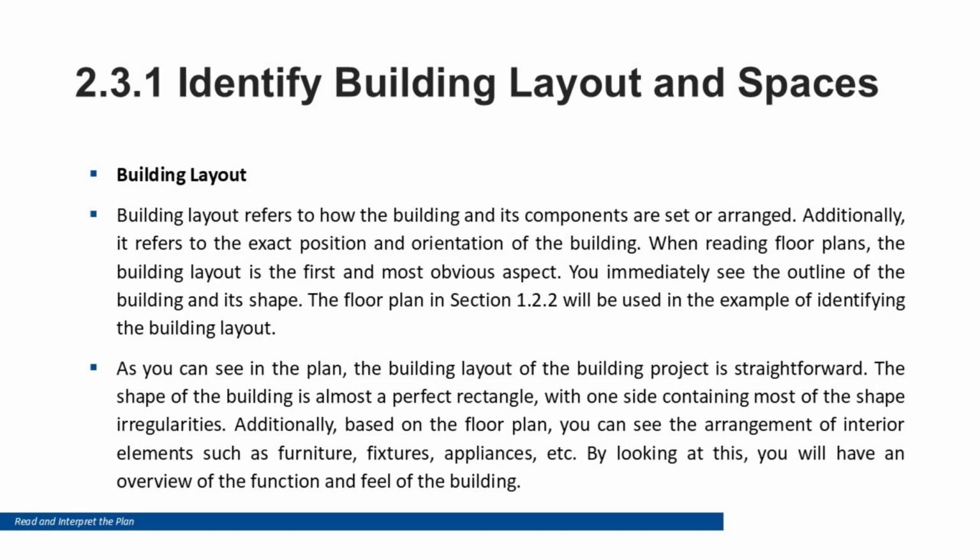To interpret the floor plan accurately, identify the scale, refer to the legend, read the dimension strings, and understand the symbols used for doors, windows, plumbing fixtures, and electrical fittings. Floor plans form the foundation for supervising internal construction work, checking compliance with layout requirements, and guiding trades such as carpentry, plumbing, tiling, and electrical installation.